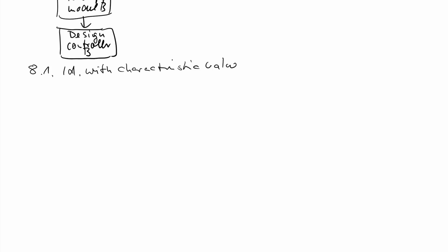This is a method which can sometimes be done manually without the help of the computer, and this is adapted to typical model types we can find in industrial processes, typical process types. The typical process types: PT1, that is a pure single PT1 system which very seldom can be found.